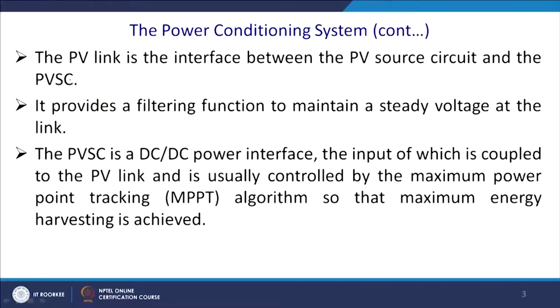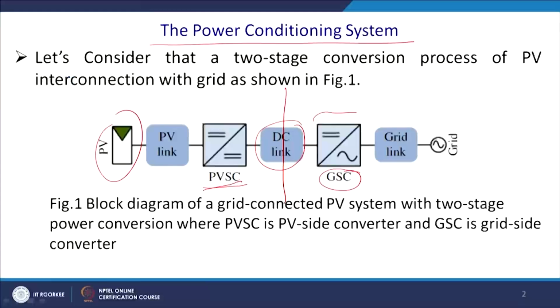if it is a pure DC it does not matter, but since it has switching, we require this. If it is a buck converter, what happens is you are temporarily making a connection off and you are bucking. Then the MPPT point may shift, and thus you require to sink some amount of current in this capacitor, and you have a ripple.